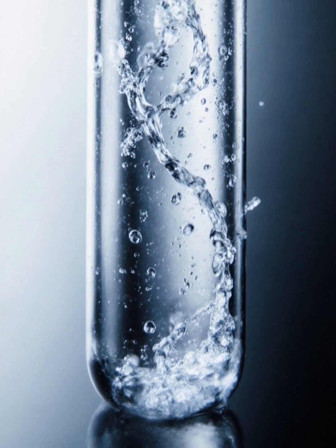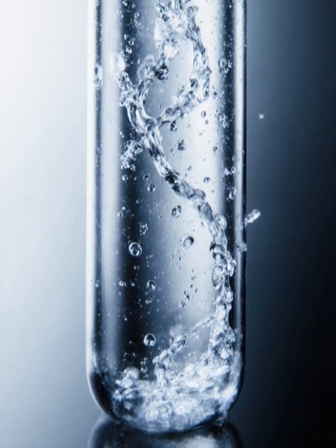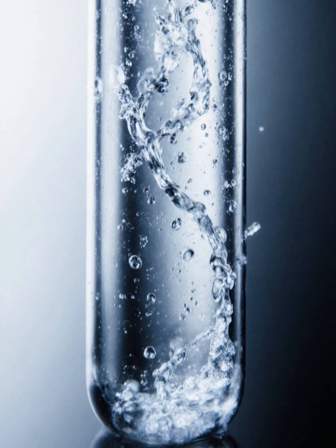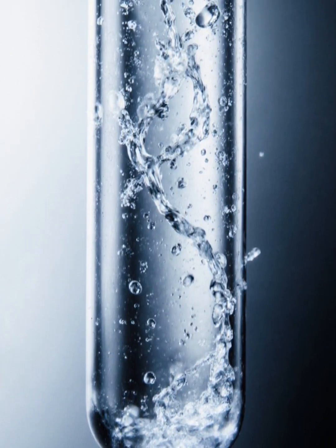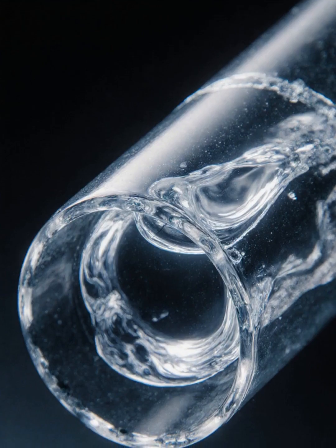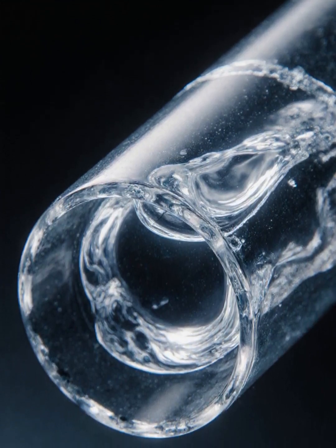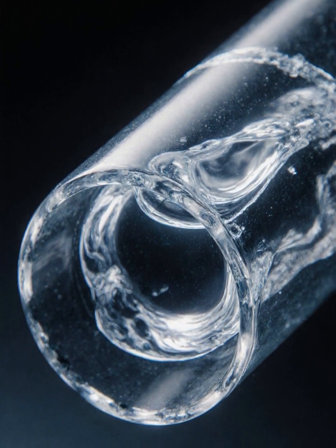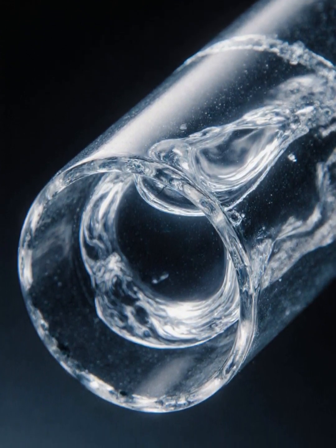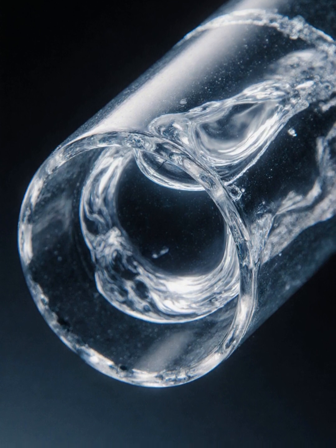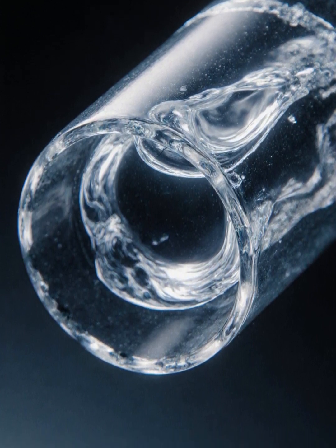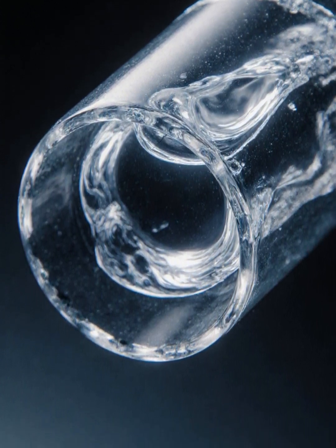This rapid, controlled oscillation creates the moving frame of reference. The fluid passing through the tube is the mass in motion. As this mass is forced to conform to the tube's vibration, it experiences the Coriolis effect, resulting in a measurable force that is the basis of the flow measurement.